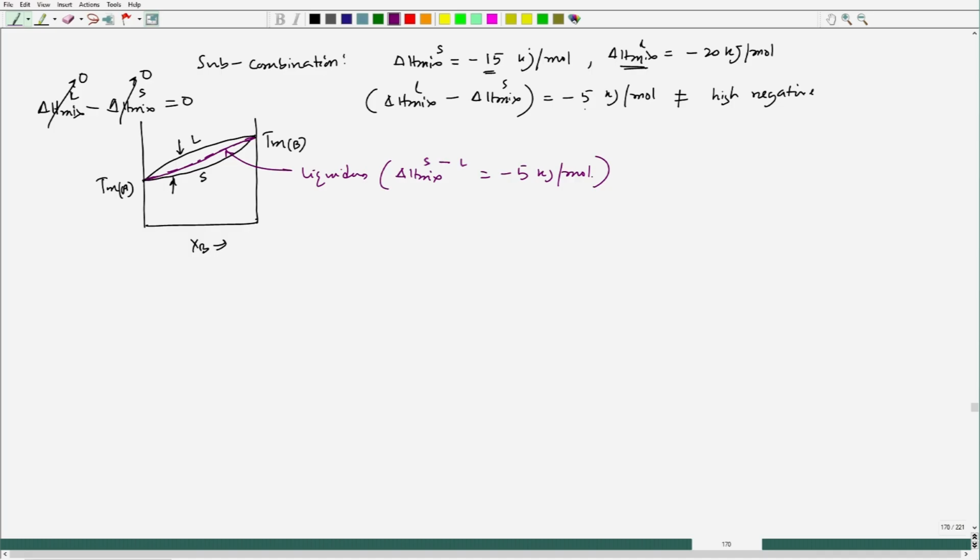I am just giving a reference, a value-wise sense of how it senses the stability of a phase. Now, you see this was the liquidus line when this difference was 0. In order to show the enhanced stability of liquid, this liquidus line has gone down, so the width has shrunk. So, the phase diagram will change.